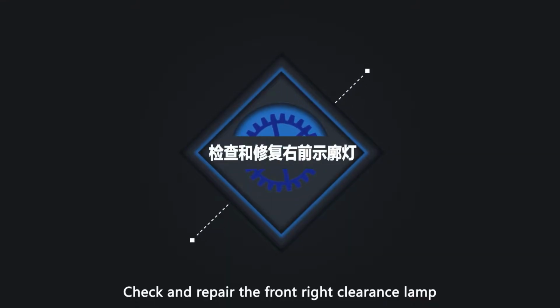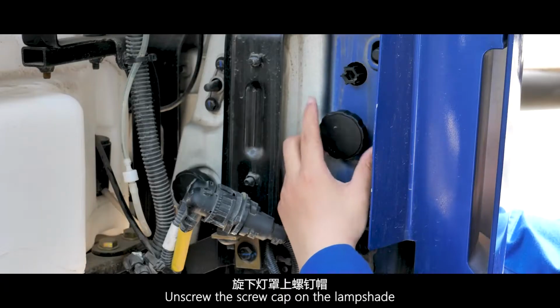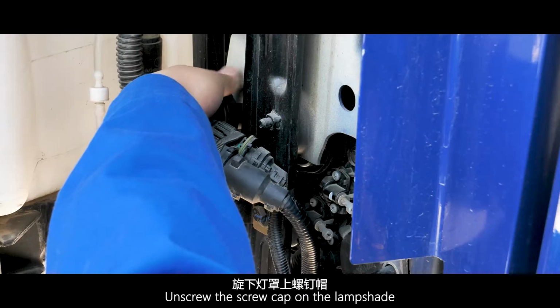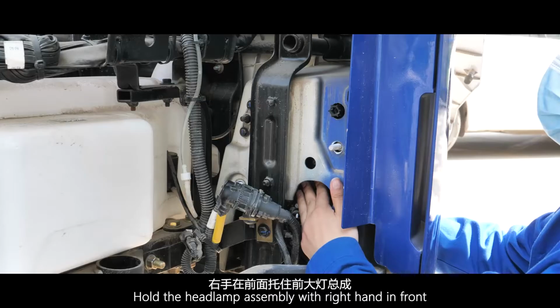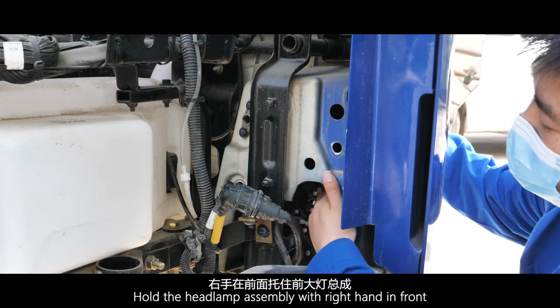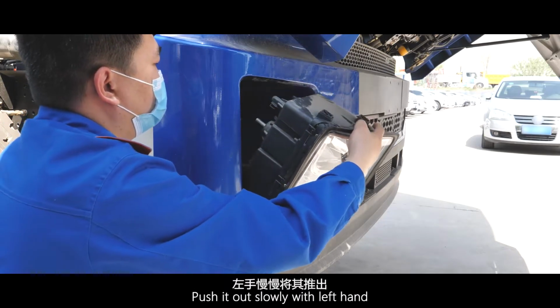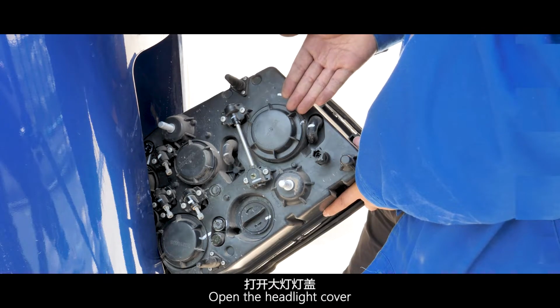Check and repair the right front clearance lamp. Unscrew the screw cap on the lamp shade. Hold the headlamp assembly with the right hand in front. Push it out slowly with the left hand. Open the headlight cover.